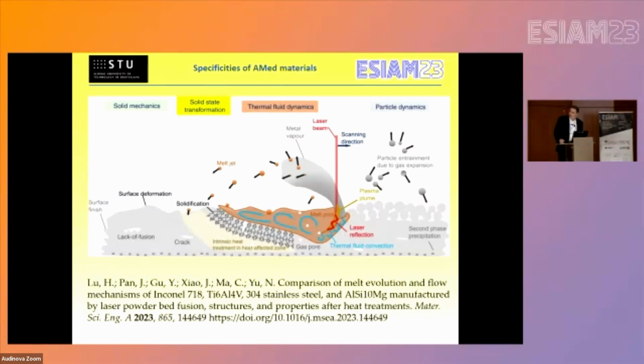The process of origin of AM material is rather different from the process of origin of conventional casting. In conventional casting, this is the liquid phase, and very slowly it becomes the first crystals and the solid phase. The opposite process occurs in additive manufacturing. All around is solid phase, and very small melting pools are in the liquid phase. From these different conditions of origin results a different microstructure, and different microstructure leads to different properties. This is not the conclusion, this is only the beginning.